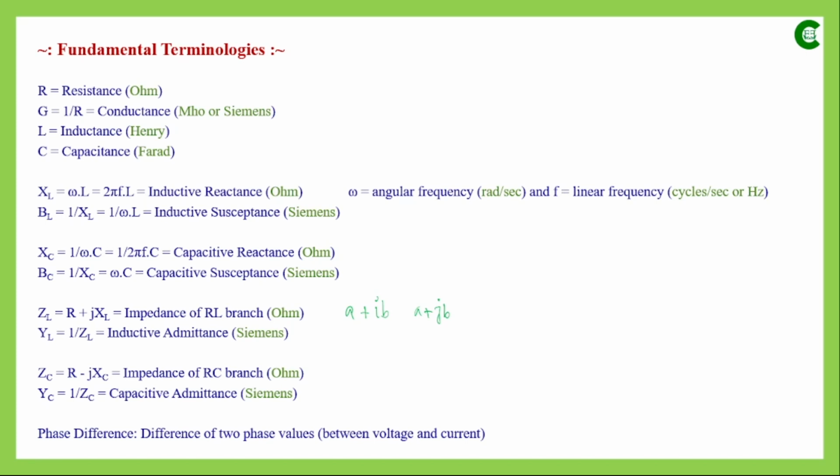So you can say the admittance has a similar nature to conductance. What conductance or susceptance does, the admittance also has the same property. Basically it is the measurement of how much the alternating current is admitted or allowed to pass through that branch, RL branch or RC branch.